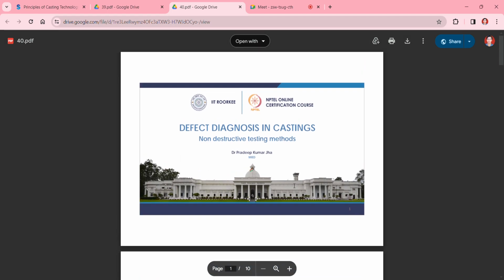So coming to defect diagnostics in the casting process, we talk about non-destructive testing methods. Why do we use non-destructive testing methods? Because we don't know if the casting we have created is a sound casting or if it has some defects inside. So we go with non-destructive testing methods because we don't want the destruction of the casting or any addition of defects inside the castings.